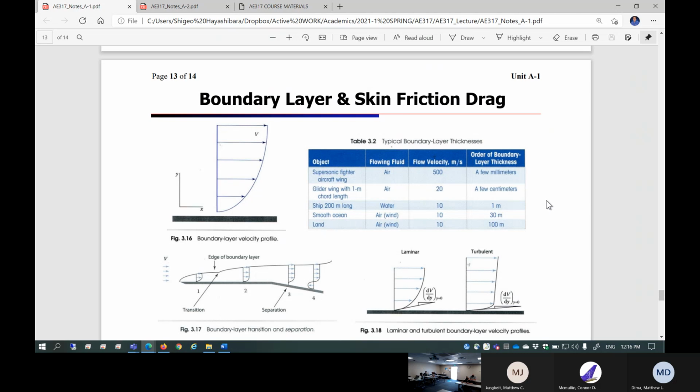That's the location where you have flow separation from the surface. Once the flow is separated, panel method cannot compute anything. So it needs to rely on the surface where the flow still stays attached. As long as the flow is attached, it is going to create skin friction drag, so you have to keep that in account.